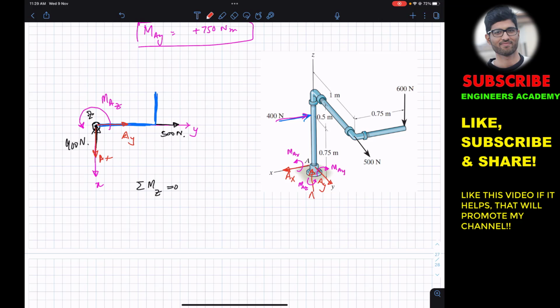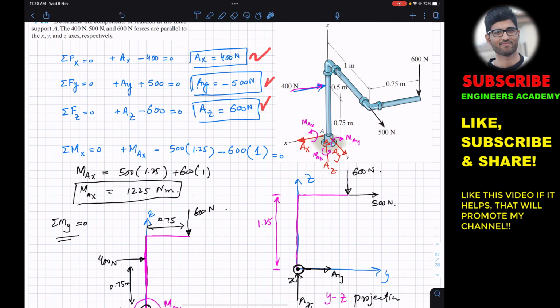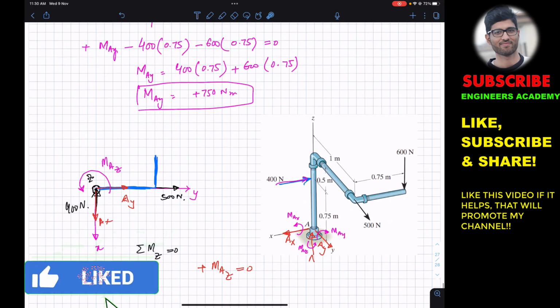So this means that there is no moment about the z-axis. So we can say that for MAZ, in all of these three forces, no one is producing the moment about the z-axis, since this one is parallel to the z-axis, this one is passing through the z-axis, and this one is also intersecting with the z-axis. So none of these forces is producing the moment about the z-axis. This means that the couple moment reaction at A about the z-axis is 0. So now we have determined AX, AY, AZ, MAX, MAY, and MAZ is equal to 0. So this is the solution of this particular problem.